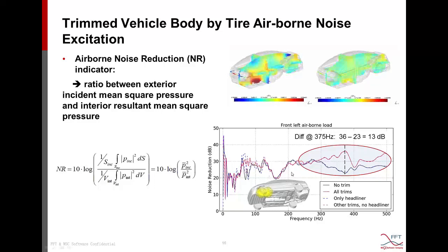Okay, so we can see here the treatment has quite limited effect below 300 Hertz, but starting from 300 Hertz, we have an increased noise reduction, as we can see here, when all the trims are taken into account. And we have this difference of 13 dB here at this frequency of 375 Hertz.